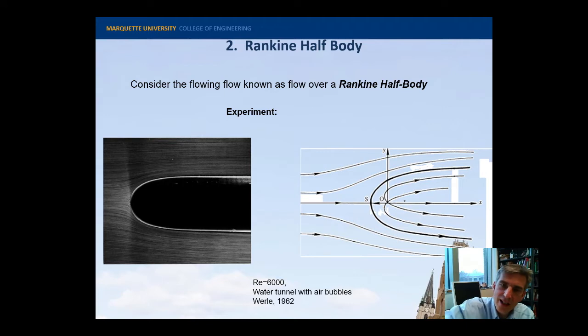So maybe you're not doing the Rankine half body, but instead you're doing a problem where you're looking at a river, and then you have a pipe, and you're injecting flow into the bottom of the river, so it's emitting this flow like a point source, and the river is combining, and you're looking at how far downstream this emitted flow is combining with the river water, on an average sense. So from this one solution, we can think of several different solutions that would represent physical phenomena.